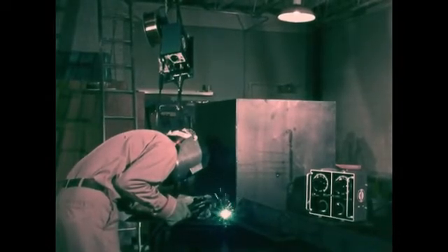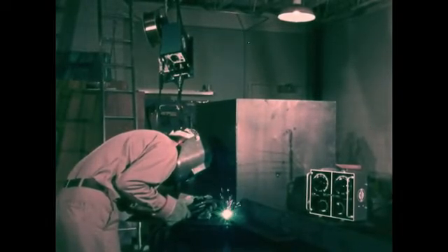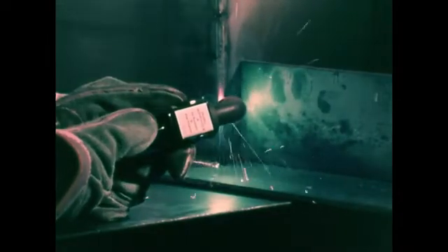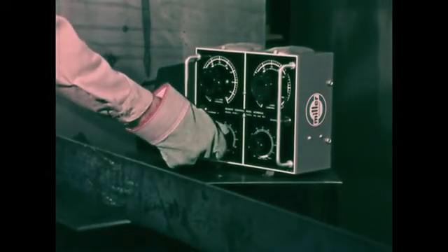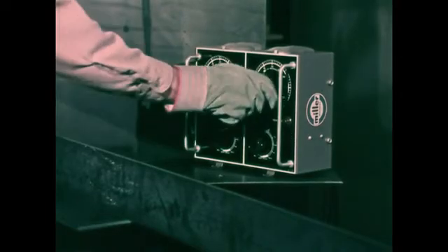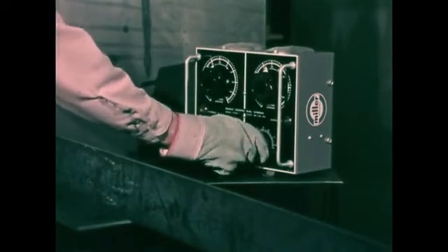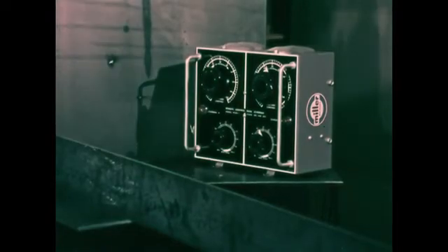On the vertical down corner weld joint, where 12 gauge is joined to 12 gauge, and on the horizontal fillet, where 1/4 inch is joined to 1/4 inch metal, different amperage and voltage values will be required. The operator sets one set of conditions for the 12 to 12 gauge and a different set of conditions for the 1/4 inch to 1/4 inch condition.